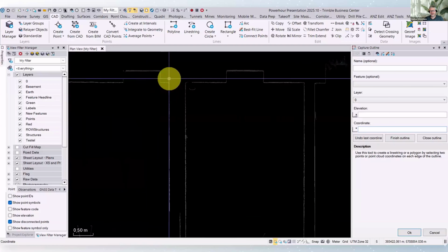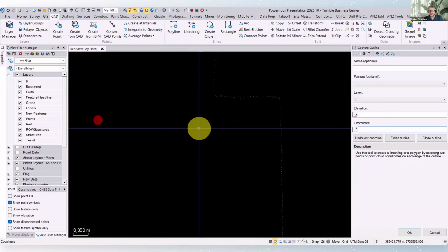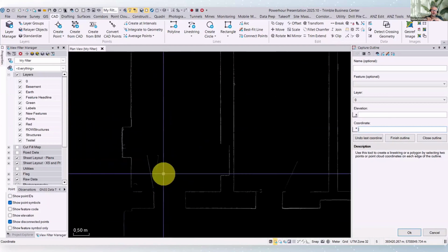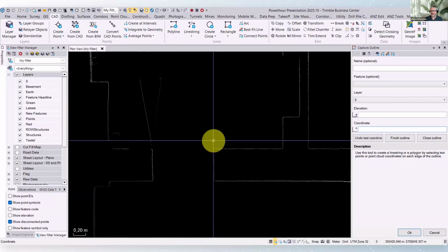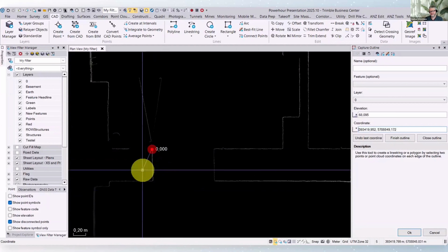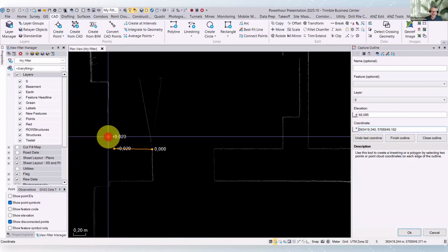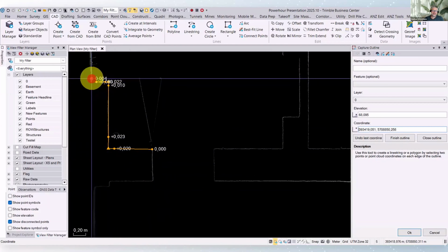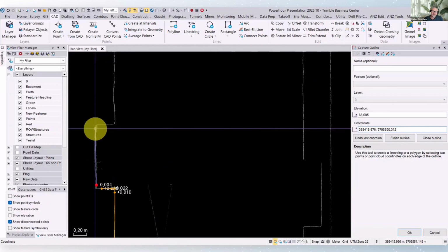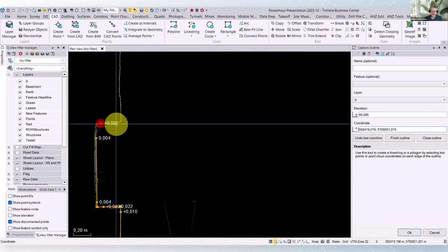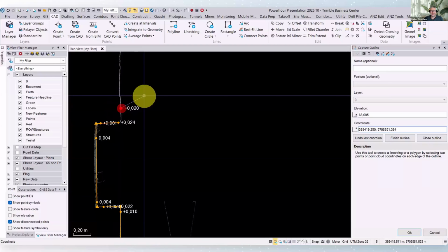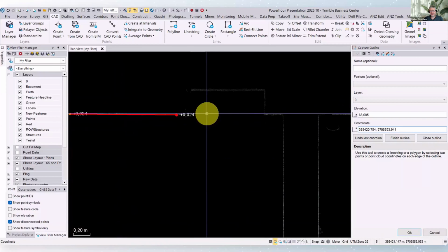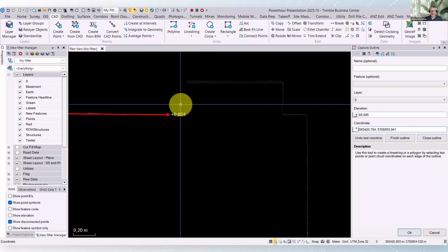Here first you see a little bit of the problems that we face in such point clouds. The corners are not corners. There are often circles. Yeah, they are plastered. So now I go on and start clicking on the point cloud. What I did here is a slice of a floor plan. We are here in plan view. That's where I like to work most. And you see 2 points on every side or on every edge.